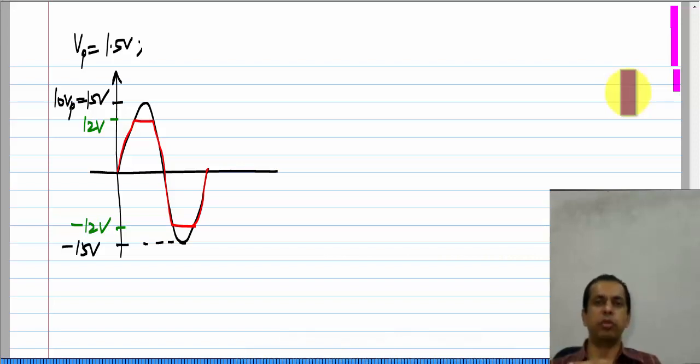And similarly, it is possible to eliminate the second supply voltage altogether and have a single supply voltage. That is, the lower voltage will be 0 volts, you connect it to ground, and the upper voltage is whatever it can be. Okay. It could be 12 volts and 0 for instance. So, that is known as single supply operation of the op amps, and that is perfectly possible. All you have to make sure is that V1, V2 and V0 in your circuit fall only between 0 and 12 volts. You cannot go negative. Okay. And it is quite easy to arrange that. I will not go into those details here, but it is possible to operate op amps with a single power supply voltage as well. Okay.